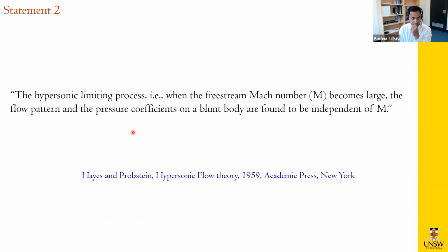The second statement is also equally important. In the hypersonic limiting process, that is when the free stream Mach number becomes very large, the flow pattern and the pressure coefficients on a blunt body are found to be independent of Mach number. This is otherwise called the Mach number independence principle, quite well accepted in the community of hypersonic flows.